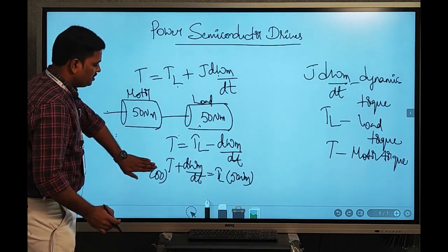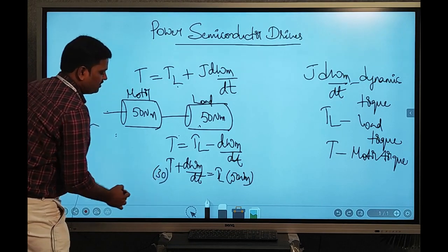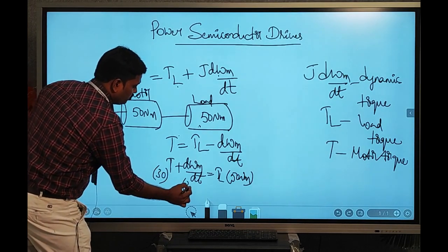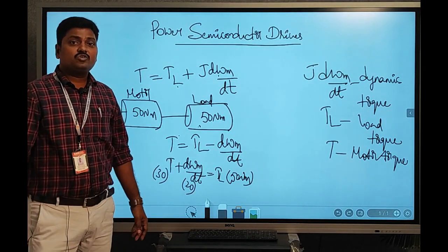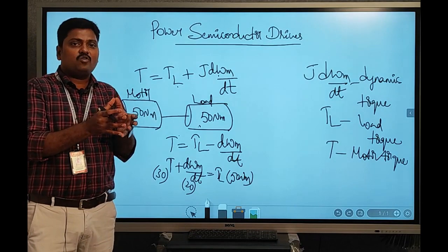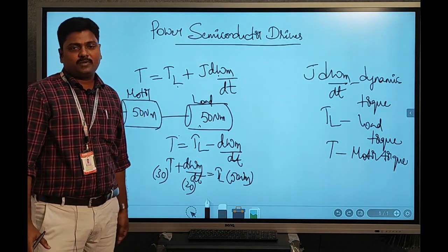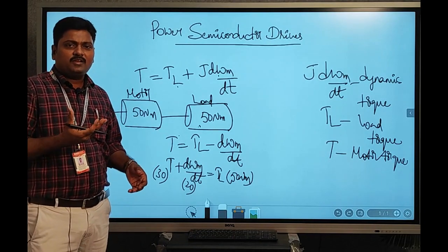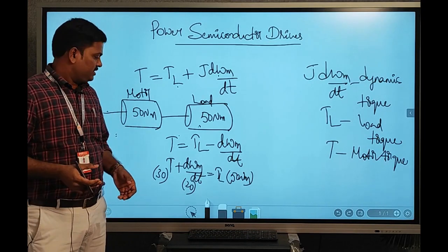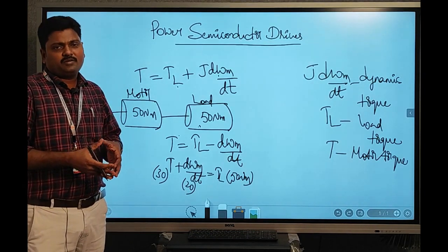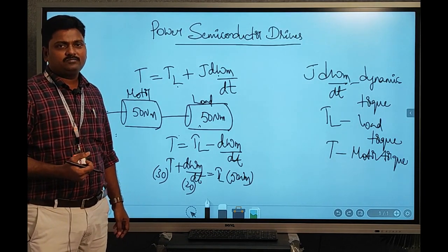So you can take a motor that can give you 30 Newton meters. The remaining 20 Newton meters can be supplied by your dynamic torque. So you can have a motor of very small size, a torque of value less than the demand torque by the load, so that the motor can be easily equipped inside the drilling machine, so it can be handy, easy to carry and all.